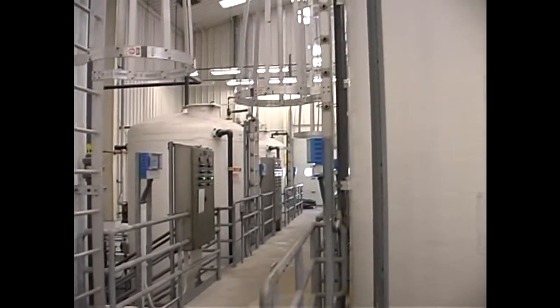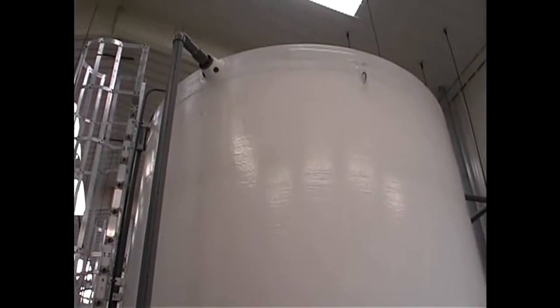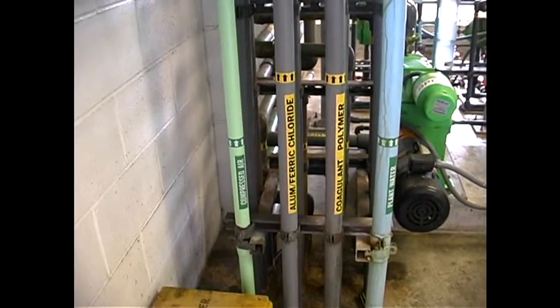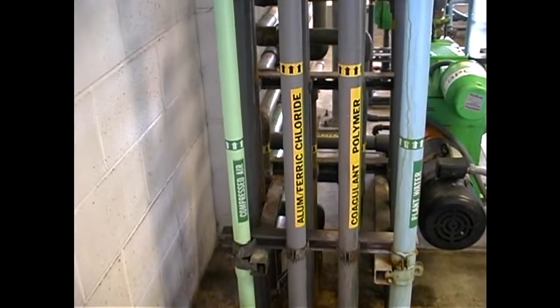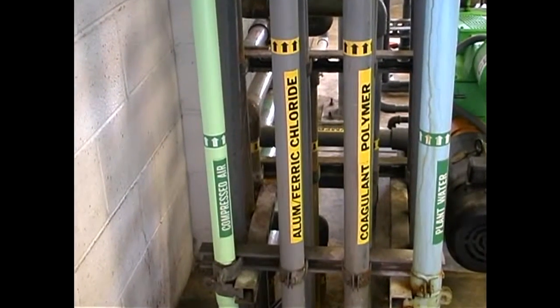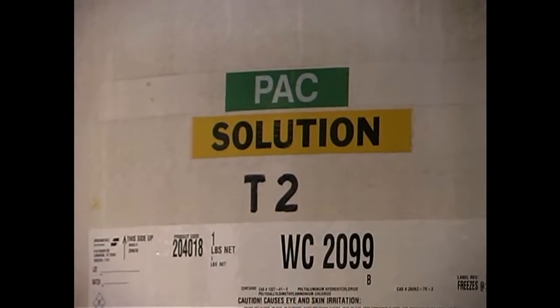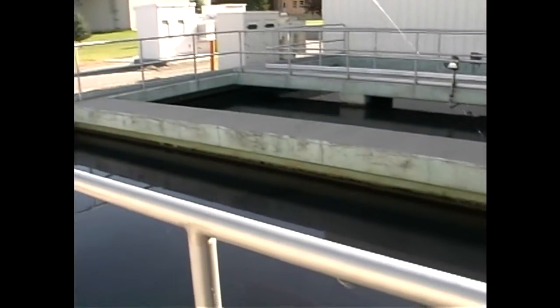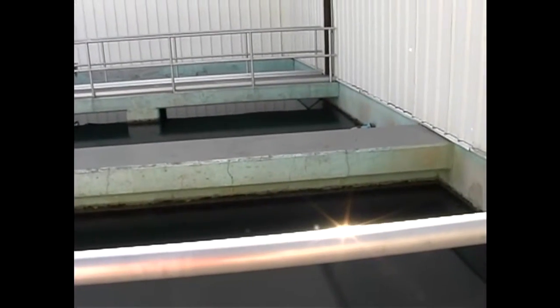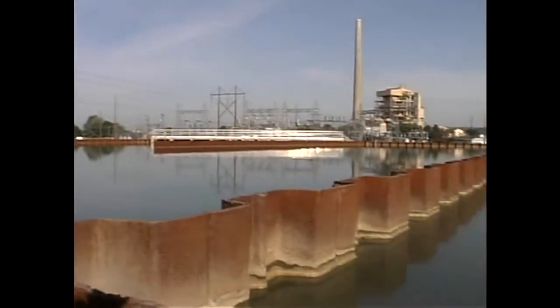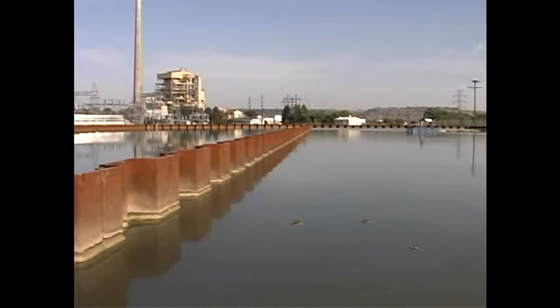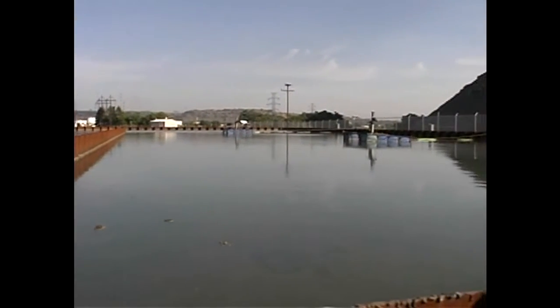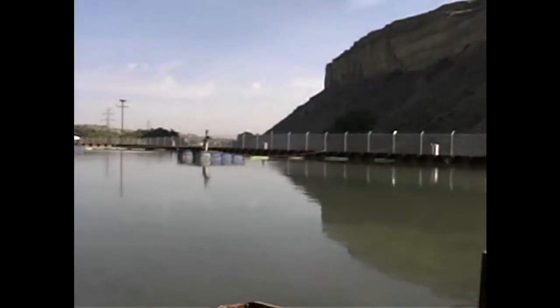The coagulants that are commonly used are aluminum or iron salts that form particulates that attach to the suspended or colloidal matter. Increasingly, polymer aluminum-based blended chemicals are being used for the removal process. The installation of these conventional gravity coagulation filtration systems solely for arsenic treatment is generally uneconomical. However, the process of coagulation filtration can be modified to remove dissolved inorganic matter, including arsenic.